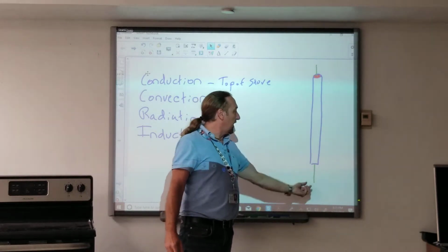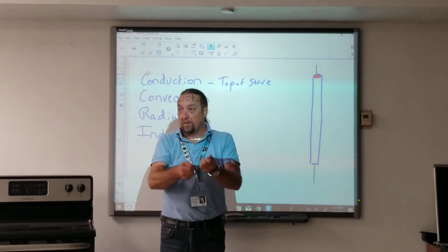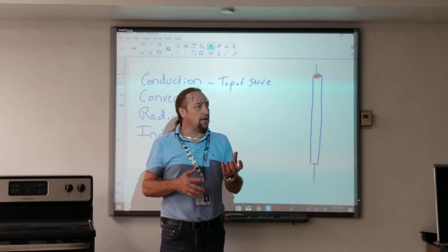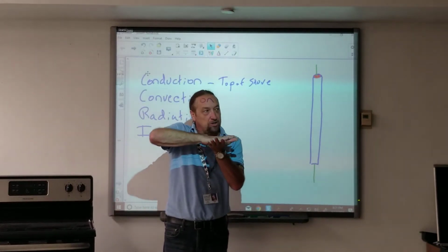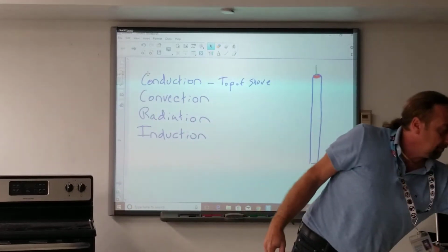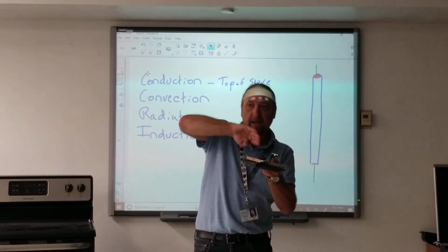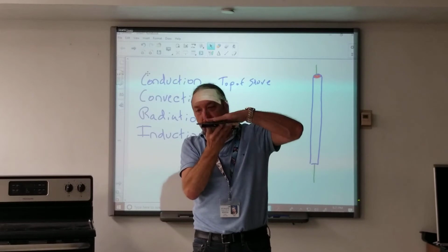So once they pull this tight and they pack the ends in, they got a machine that coils it around into the loops and makes all the bends, but it's still round. Once they do that, they take another machine and just slam it down, and actually the top of those elements are supposed to be flat. So when you look at the underside of the element, you'll see it has a curved edge.